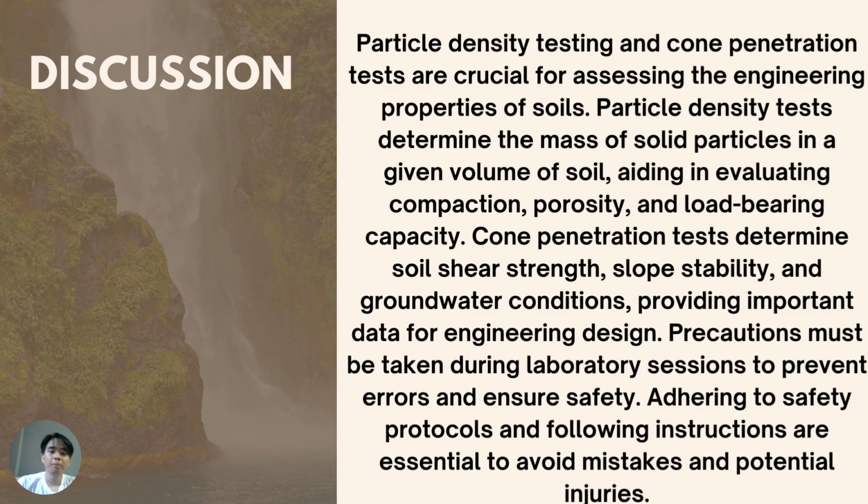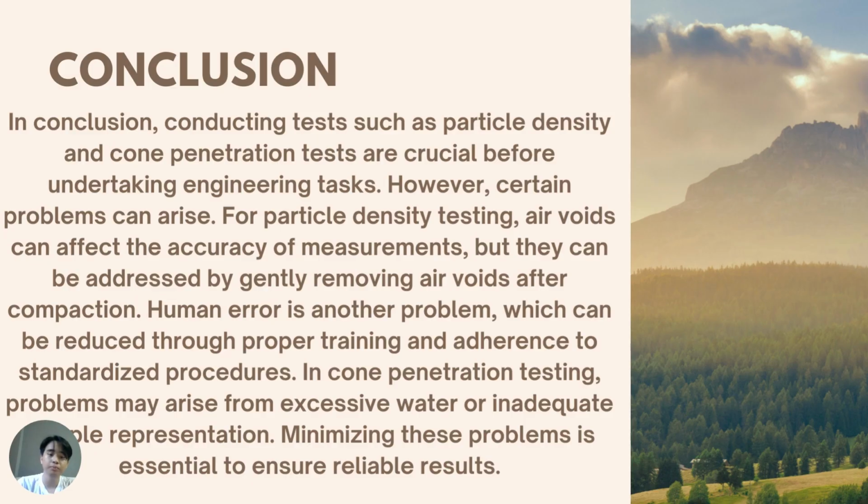For the discussion, particle density testing and cone penetration tests are crucial for assessing the engineering properties of soil. Particle density tests determine the mass of solid particles in a given volume of soil, aiding in evaluating compaction, porosity, and load-bearing capacity. The cone penetration test determines soil shear strength, stability, and groundwater condition, providing important data for engineering design. Precautions must be taken during the laboratory session to prevent errors and ensure safety. Adhering to safety protocols and following instructions are essential to avoid mistakes and potential injuries.